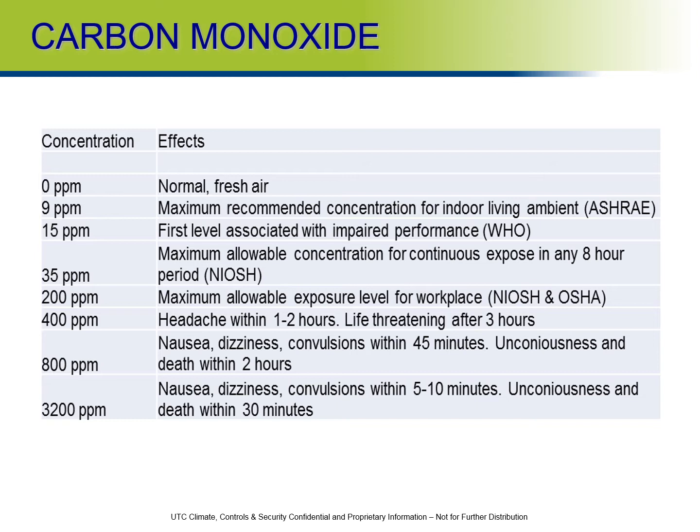So this kind of breaks down the concentration of carbon monoxide and the effects it'll have on the normal body for you to be able to use in the field. Now, again, 9 parts per million is pretty much the standard that we've all come to realize is the maximum allowable limit for a living space. It's what we've been using for years. Anything outside of that 9 parts per million creates a hazardous living space and would require the unit to be shut down until a remedy is found or the problem is fixed.